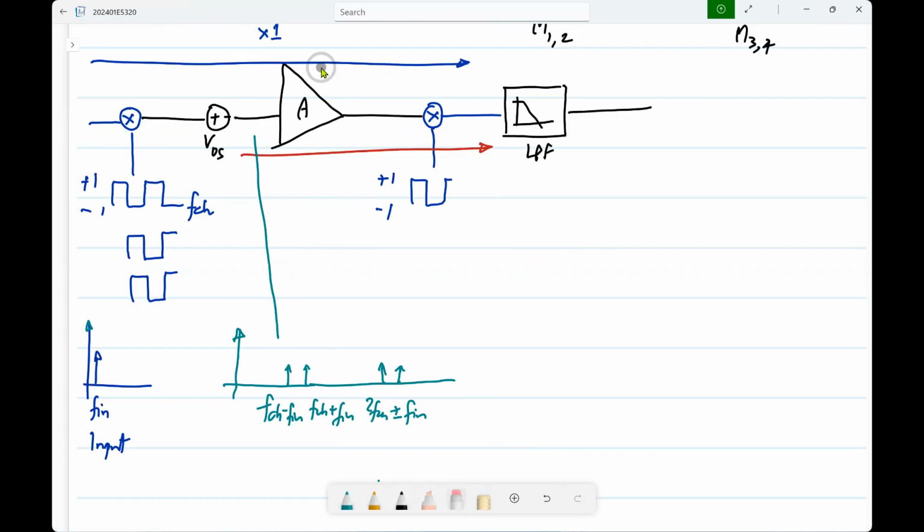Okay. So essentially, whatever low frequency signal is here will get translated up to the chopping frequency and then get translated back. If this block has a lower gain at the chopping frequency compared to DC, then overall the gain has effectively reduced. The analysis is a little more involved. You can do it in detail, but basically that's what happens.